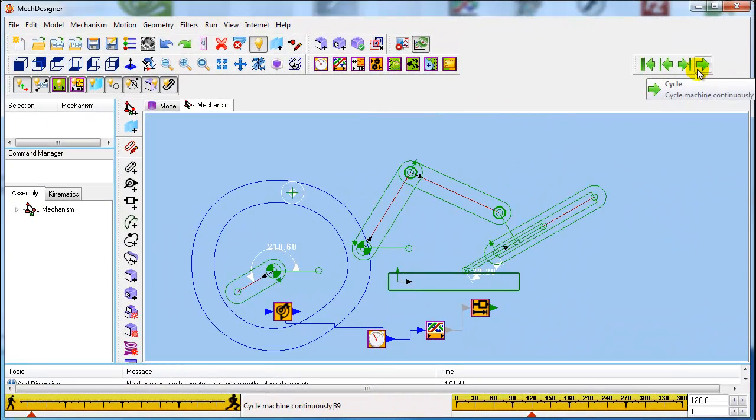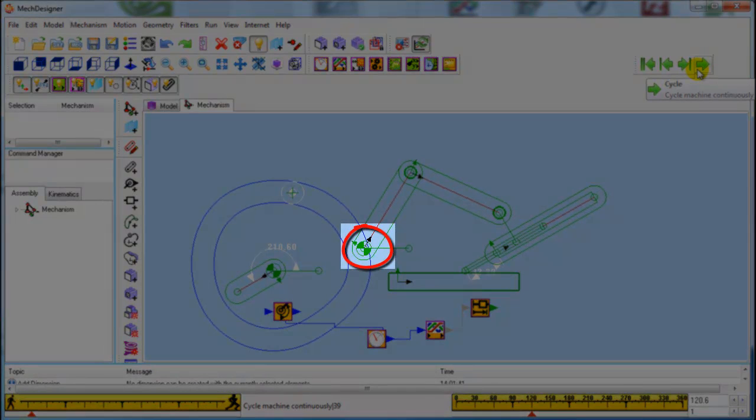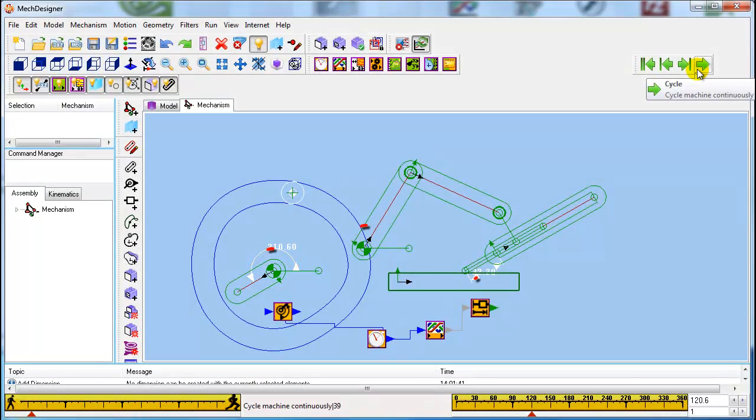Before we start the design, what do we need to sketch in the mechanism frame to locate and align the mechanism parts? We need a line to align the slideway for the pusher. We need a point to position the pivot bearing for the cam follower mechanism. And we need a point to locate the center of the camshaft. So we need 3 sketch elements in the base part to locate and align this cam mechanism.